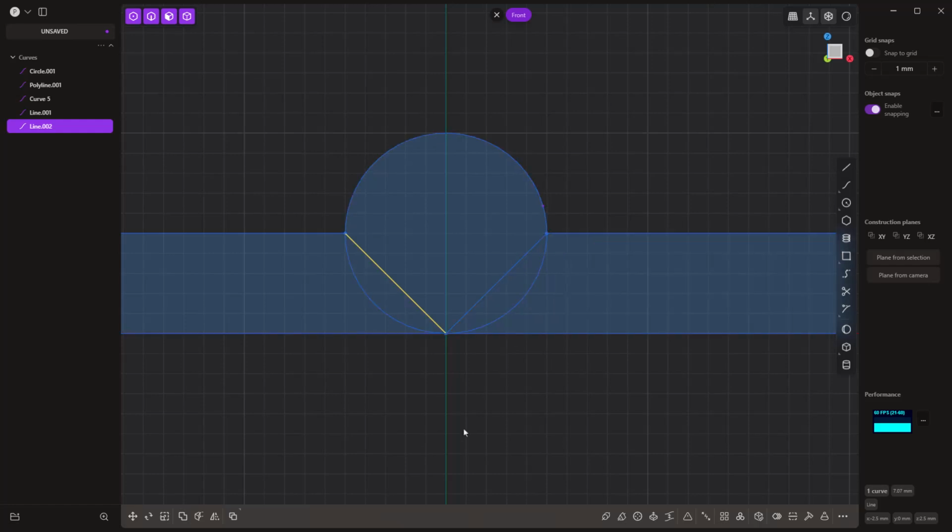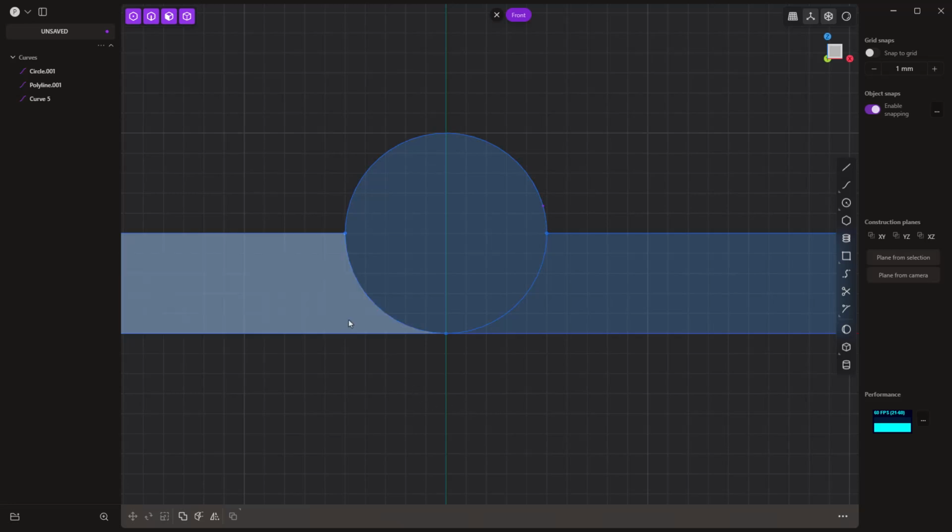Now, you don't have to do this, but if you want it to print a little nicer, especially at smaller sizes, when you're talking 5 to 10 millimeters, then having an angle like that or a taper up away from the build plate is going to be better than having a true arc in that section. For our purposes, I'm not really concerned with how it looks, but as you begin experimenting with these on your own, that's something that you should consider, is just kind of going up from the build plate at an angle, and you'll get a sort of a better or nicer, cleaner look to that 3D print.